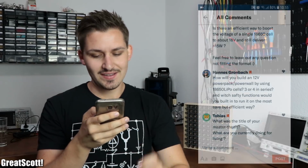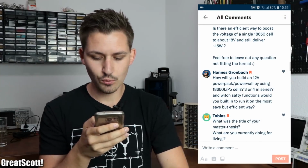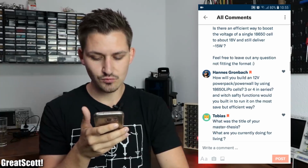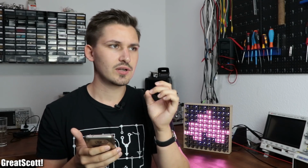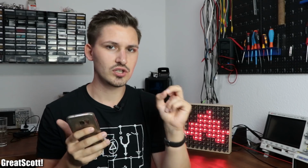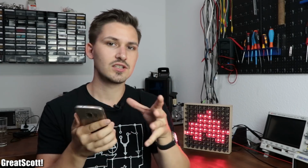Okay, next question from Hannes Gronbach. How will you build a 12 volt power pack / power wall by using 18650 Lipo cells, 3 or 4 in series? Which safety functions would you build in to run it in the most safe but efficient way? To get a 12 volt output, I would definitely go with 4 in series, because with 3 in series, I don't have the exact numbers right now, but I think you would be getting too close to 12 volts to just use a buck converter. So with 3 in series, you would need a buck boost, and for 4 in series you would just use a buck converter.